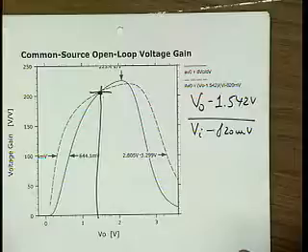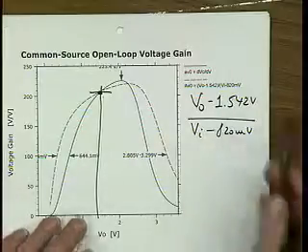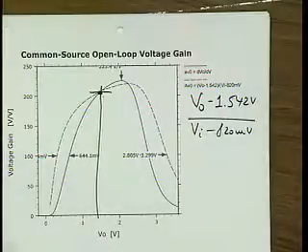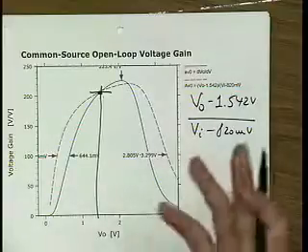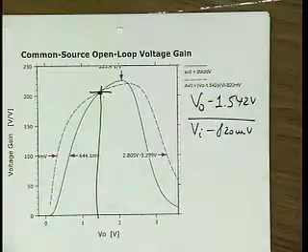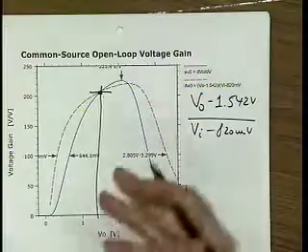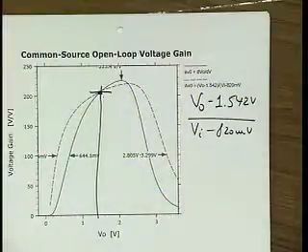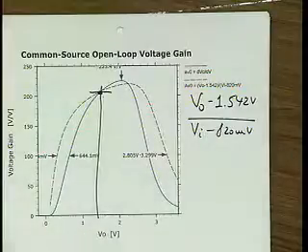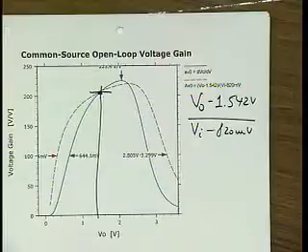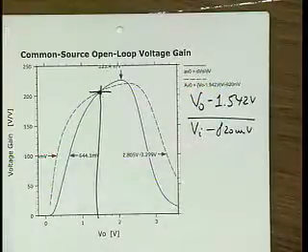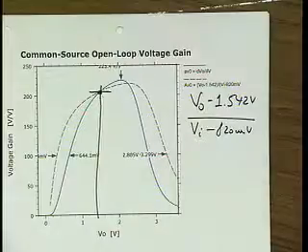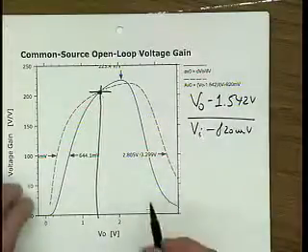Okay? Now, most of the time this is not a problem at all, because most of the time we use fully differential amplifiers, and then these two numbers are 0, and you don't need to fuss with all of this. That's precisely the reason why we use differential amplifiers, because then they don't have a built-in offset, at least not beyond the random device mismatch offset. Systematically, they are designed for 0 offset. A common source amplifier, of course, is not. And because here I wanted to make a simple example, I used the common source amplifier, and then we run into this complication. So sometimes simple means complicated. Okay, so most of the time that's not going to be a worry.